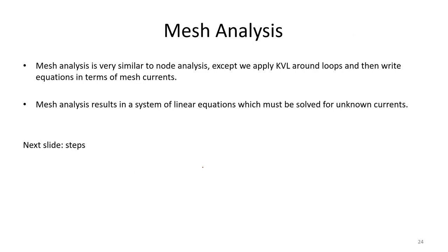So, as we mentioned before, mesh analysis is very similar to node analysis, except we are applying Kirchhoff's voltage law around the loop, and then we are writing equations in terms of mesh currents. So we write what's called mesh equations. Mesh analysis gives us a system of equations for current. So let's go ahead and walk through the steps of mesh analysis.